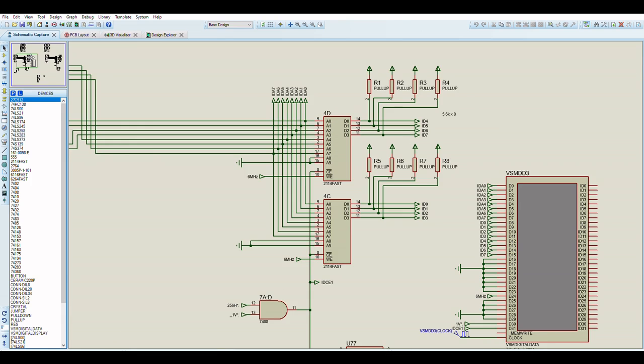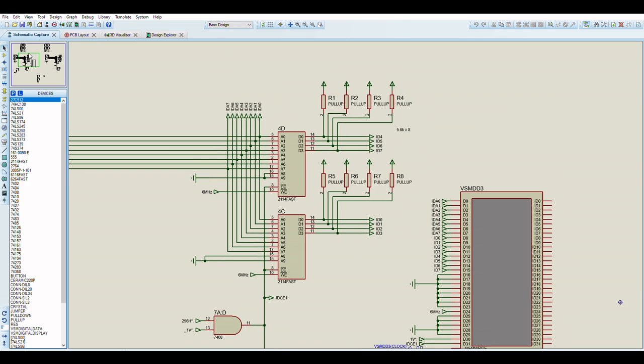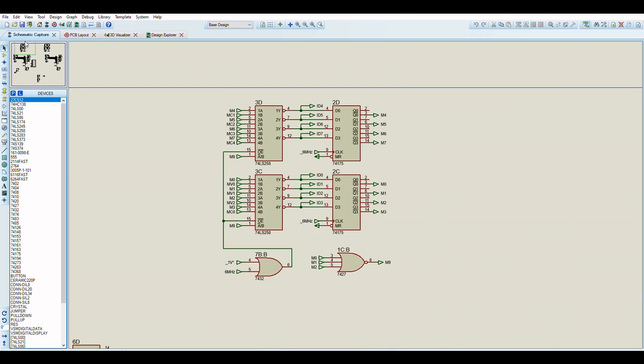If this is not outputting anything, if the output is not enabled, and the RAMs are enabled for writing, the weak pull-ups will pull the signals up, and that's how the RAMs get filled with FF.